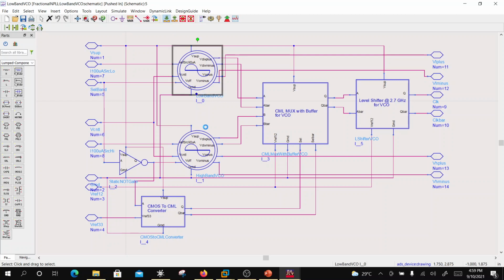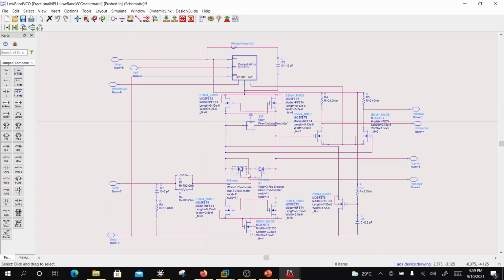And if I go inside, I see an inductor here, and then 2 varactors here. So these two form a tank circuit, and then it has a certain loss, and then there are these cross coupled transistors both at the top and the bottom, PMOS and NMOS. They provide negative resistance to compensate for the loss of the tank circuit, so that the oscillations should continue to take place, right? It should not just damp out. So this is how a VCO works.